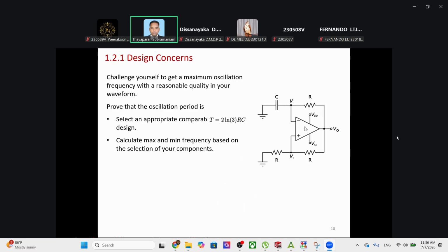As far as the operational amplifier is concerned, you have both positive feedback and negative feedback. So which should work better, or which should work at the higher frequency? The op-amp and the positive feedback path of the comparator should work better. That means the comparator bandwidth should be higher compared to the oscillation frequency here.